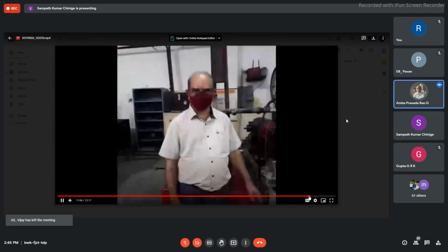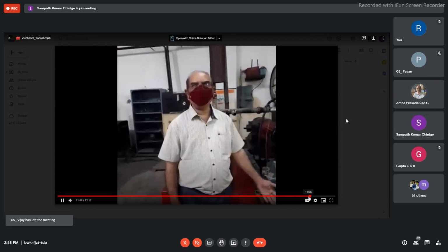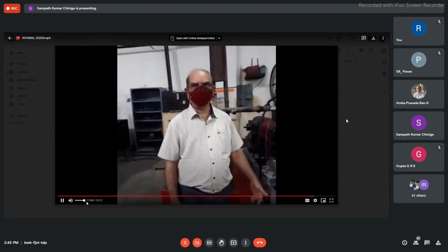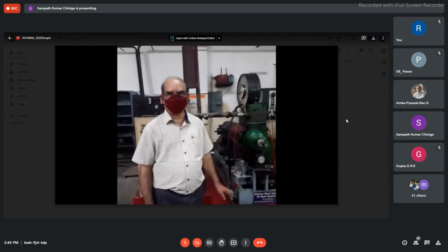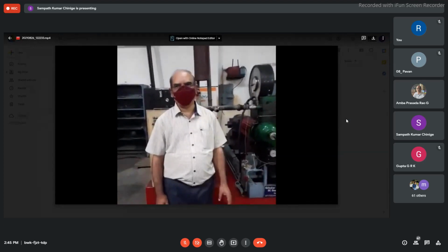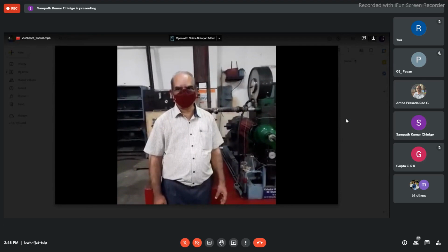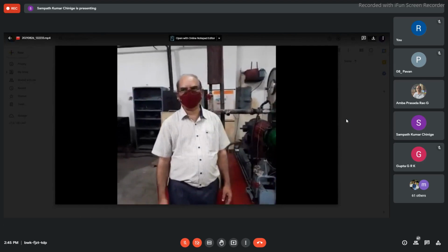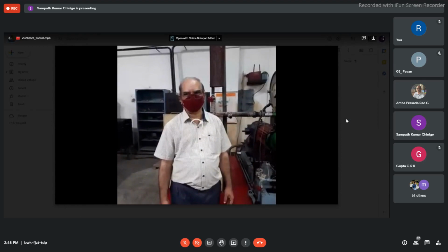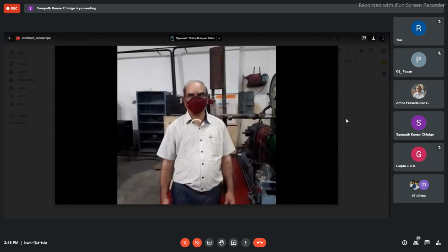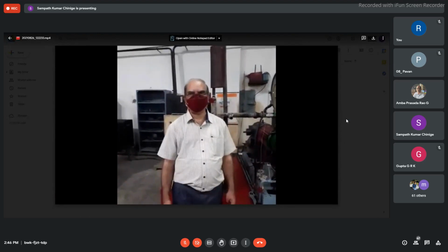Yeah. So likewise, every step you will change the load. We come to 1 kg meter and the next load is 1.5 kg meter, till we come to 2.4 kg meter on the top. So likewise we get about 6 readings. These 6 points will help us to draw graphs with respect to various parameters like thermal efficiency, both brake thermal efficiency and indicated thermal efficiency, mechanical efficiency, and specific fuel consumption versus brake power.